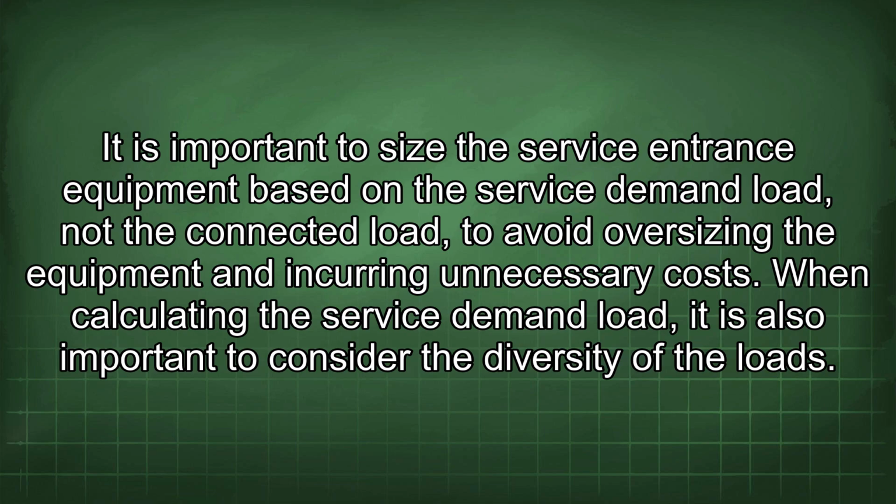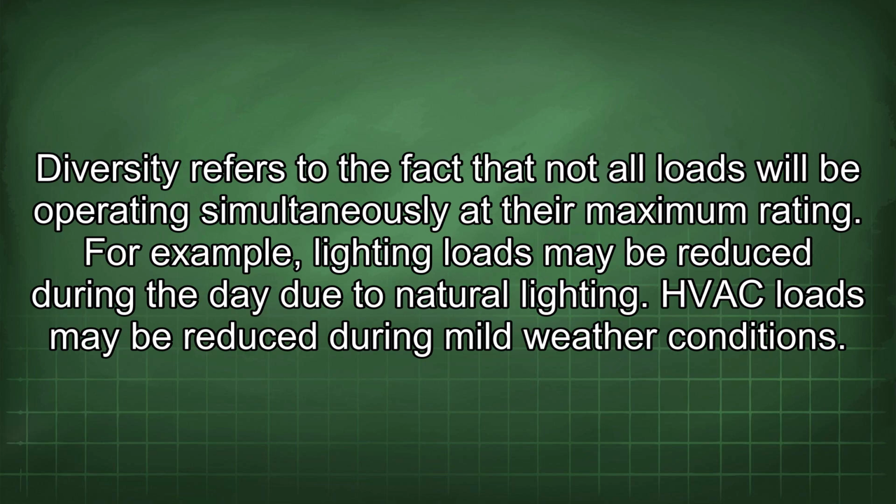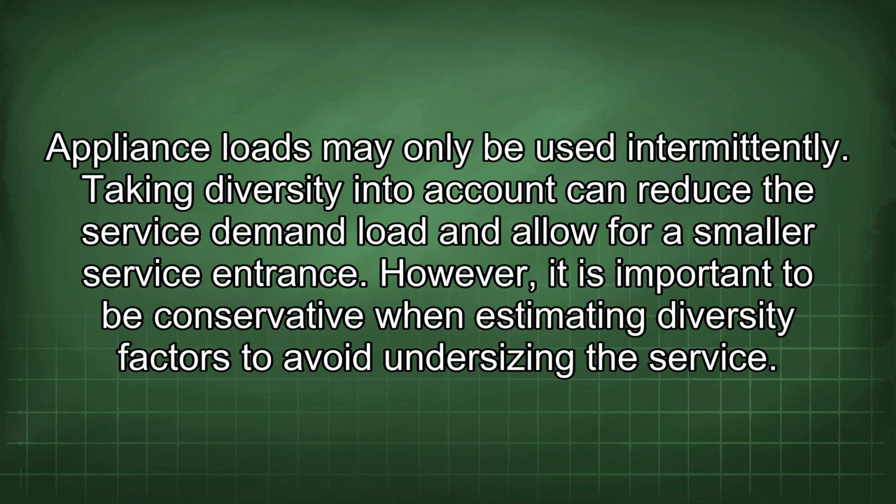When calculating the service demand load, it is also important to consider the diversity of the loads. Diversity refers to the fact that not all loads will be operating simultaneously at their maximum rating. For example, lighting loads may be reduced during the day due to natural lighting. HVAC loads may be reduced during mild weather conditions. Appliance loads may only be used intermittently. Taking diversity into account can reduce the service demand load and allow for a smaller service entrance. However, it is important to be conservative when estimating diversity factors to avoid undersizing the service.